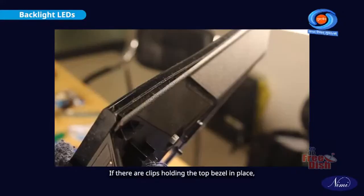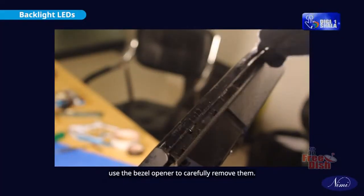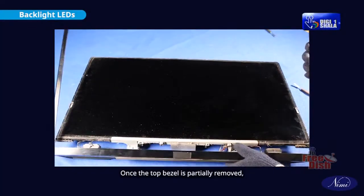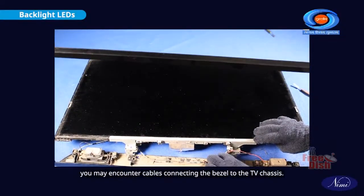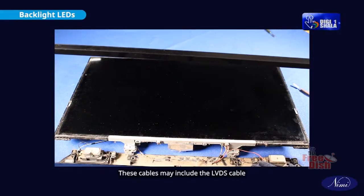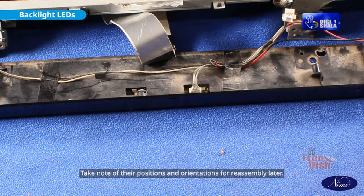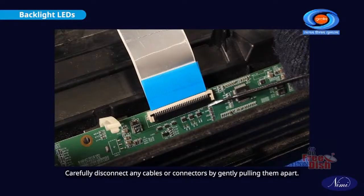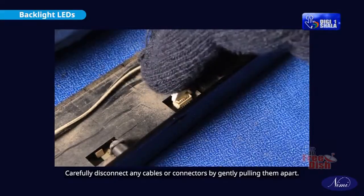If there are clips holding the top bezel in place, use a bezel opener to carefully remove them. Once the top bezel is partially removed, you may encounter cables connecting the bezel to the TV chassis. These cables may include the LVDS cable for the LCD panel, control buttons, or LED indicator lights. Take note of their positions and orientations for reassembly later. Carefully disconnect any cables or connectors by gently pulling them apart.